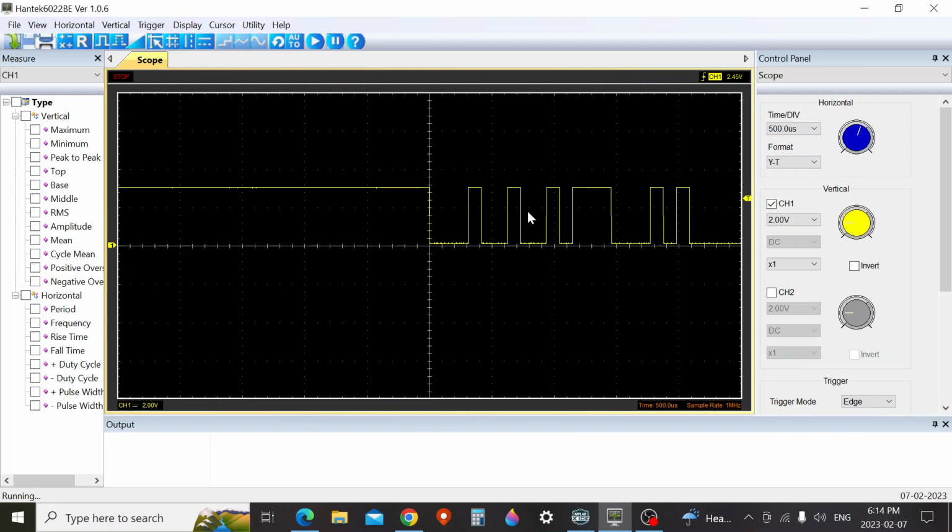So if it looks like things are off a little bit, it could be my oscilloscope. Anyhow, there's about 300 microseconds, therefore it's probably 3 clock pulses or 3 bits of data right there. And they're all high. So that'd be 3 ones right there, and that'd be 3 zeros there, and there's probably a 1 high and a 1 low. So we're going to read this.